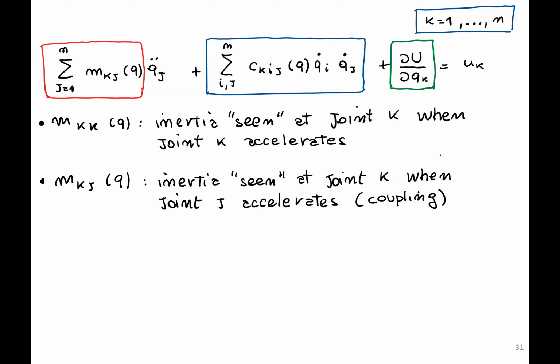So if I move it, think about a 2 degrees of freedom robot, and I'm moving the first degree of freedom with my hand, and the other one will do like this. And this means that it accelerates in the other direction. And this is a fact that shows that there are inertial couplings. So the motion of one joint is influenced by the torque, for example, applied from another joint, on another joint axis.